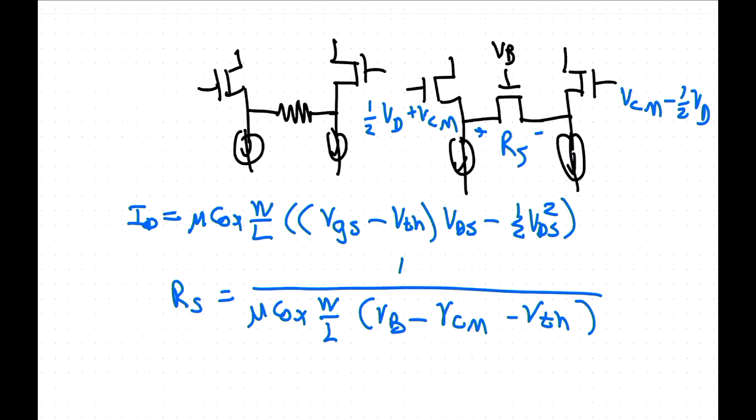There are other ways. Would it be better to use a transmission gate? Yeah, so it is. The right-hand solution there is restricted in the voltage you can apply at the input because it needs to be in the triode region. So can you put in a transmission gate? You'd put a P and an N in parallel in order to extend that range.